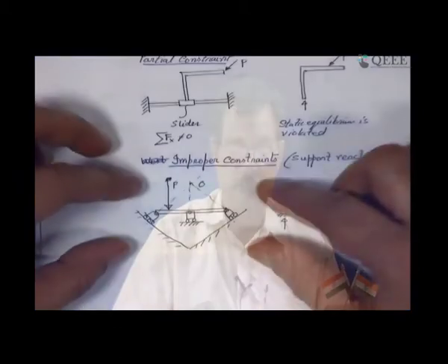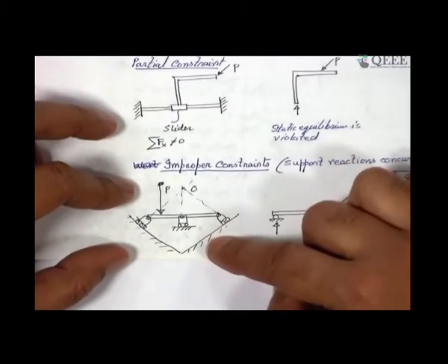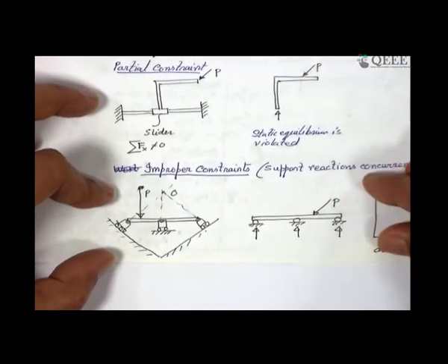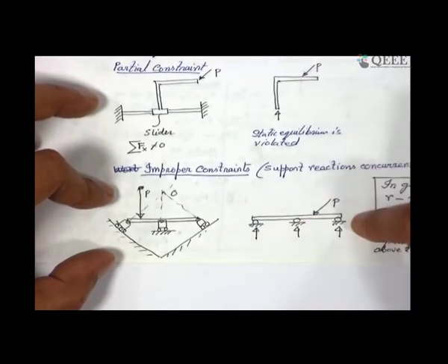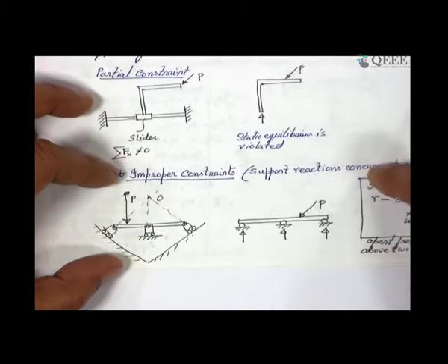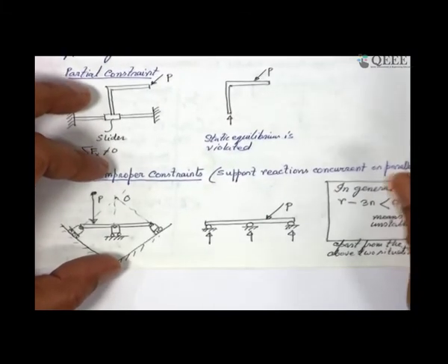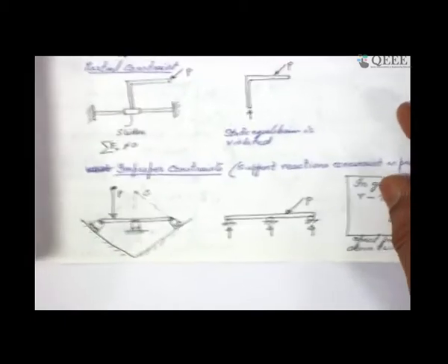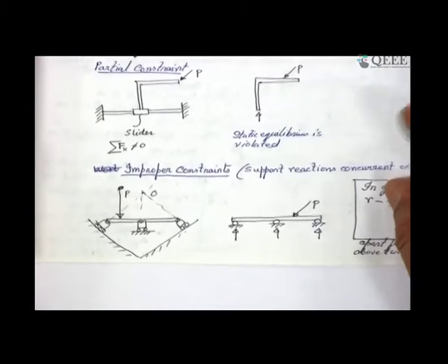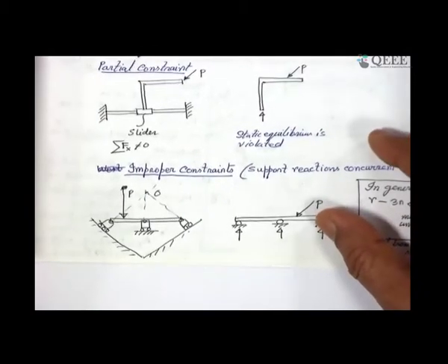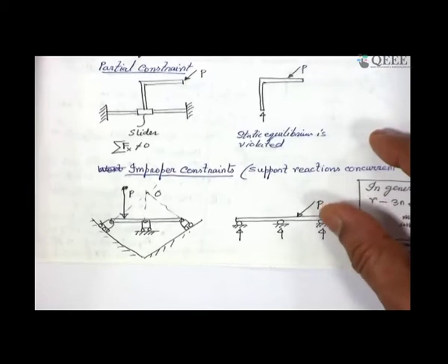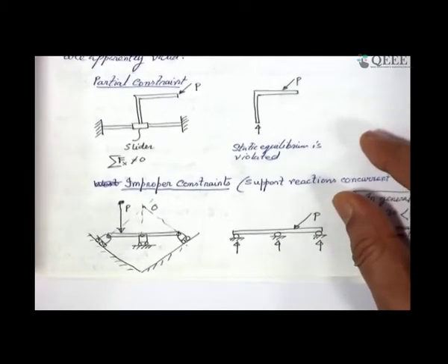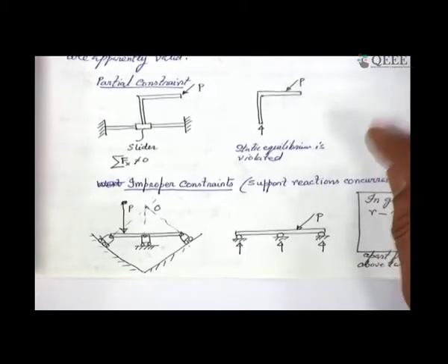For example, even if the calculation shows that structures with 3 rollers, or a beam sitting on 3 rollers, are stable as per the calculation, it appears to be stable, but it is not. And also, even if the equation is satisfied, even if they are found to be statically determinate, the question of finding out that determinacy does not arise if the structure is unstable.